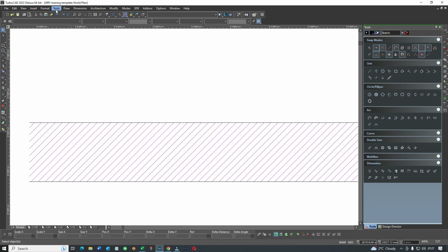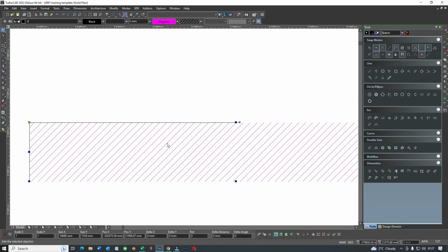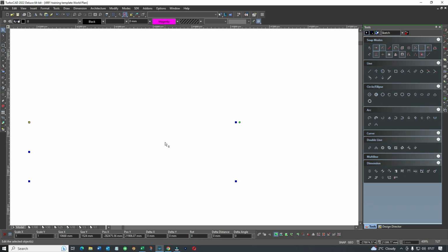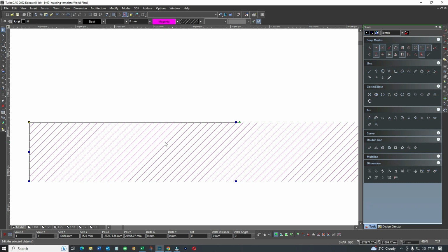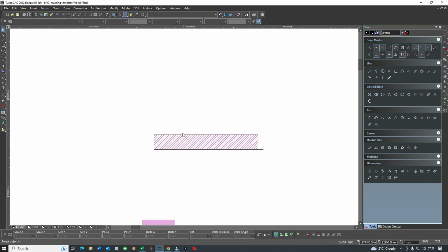So that's if you wanted to use the drop down menu. But again, to change the draw order here, hold down Shift, Page up, Shift, Page down. So again, useful tools. So whenever you do any kind of fill, say you're doing a house and you're doing a fill on the roof tiles, etc., and you want to make sure that the outline of the roof isn't covered with all these miniature little lines, just change your draw order.